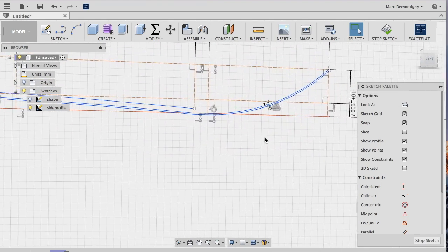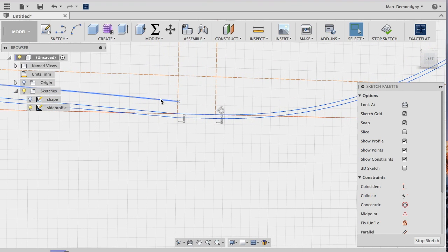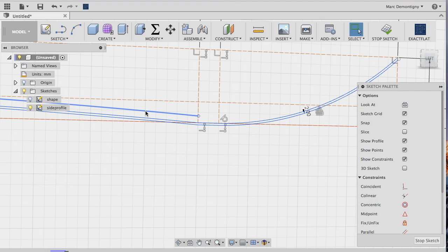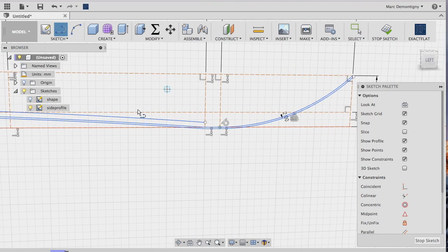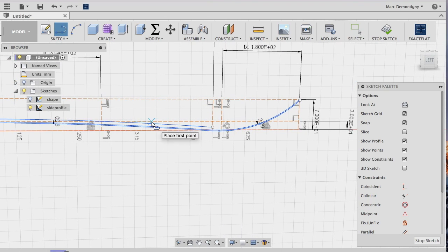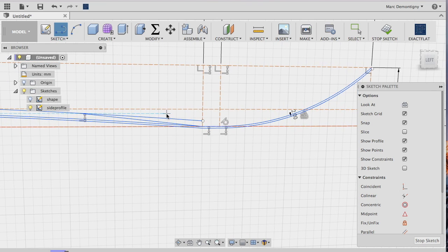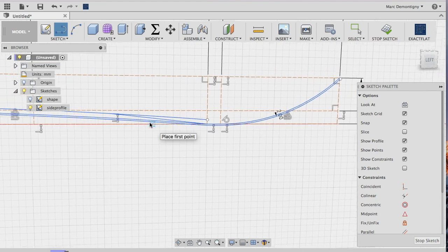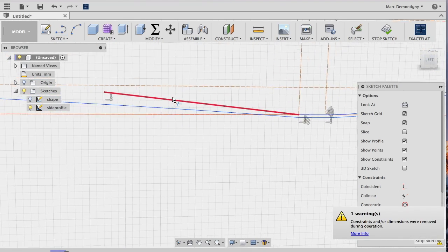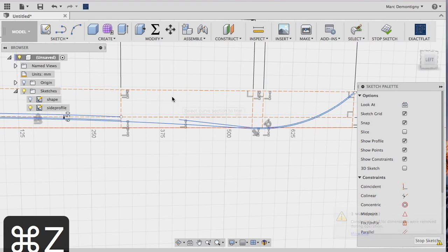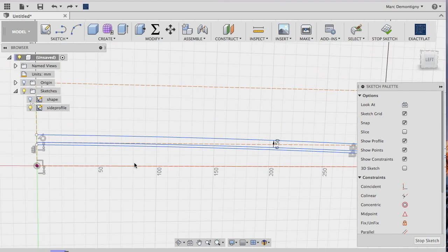Okay, so you can see there's 2 lines there. So what I want to do is I want to blend this 6.5 millimeter core down into the 2 millimeter tip. For the sake of brevity, I'm just going to do that in a very simple way. So I just drew a line from there to there. We're going to hit the T button, and we're just going to trim away some of the stuff that we don't need. Oh, that was a little bit too much. Do that.